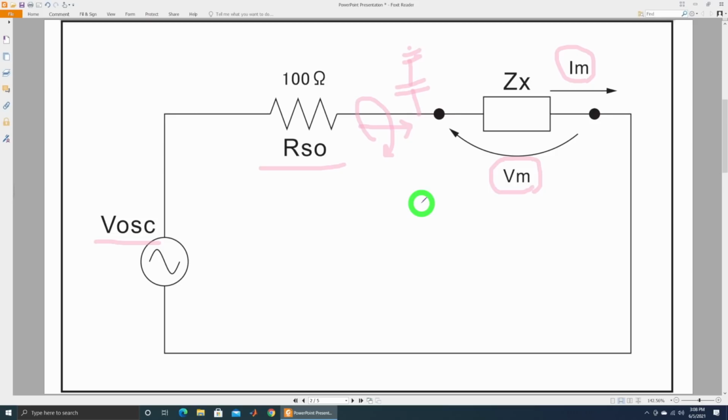And every time you move the cables around, the 2 cables that can get close to each other are going to mutually couple to each other. And that's going to throw your measurement off too. Meaning that it would be very difficult to build something that has a repeatable measurement performance because of the variation in the setup every time you want to measure.